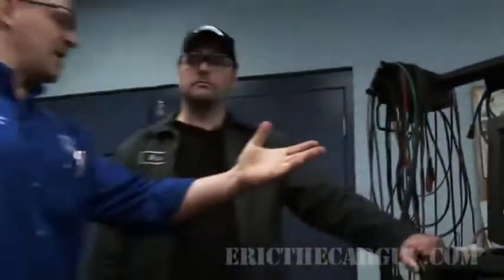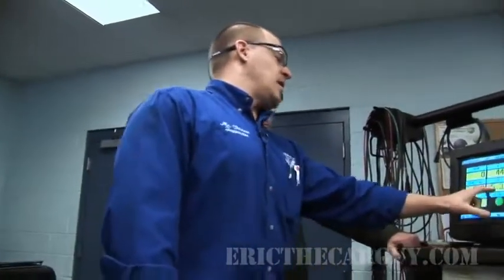So you don't want to overanalyze this high CO number on an initial startup. You want to let it run for a bit. Normal out. Can you hold that at 2,000 for me? And that's going to hasten that process, speed up the process a little bit.